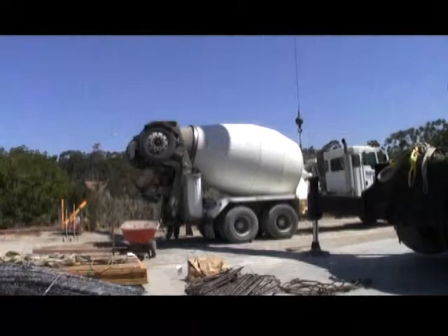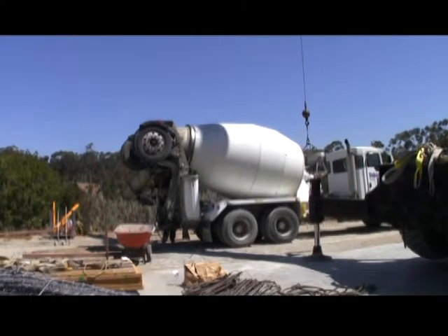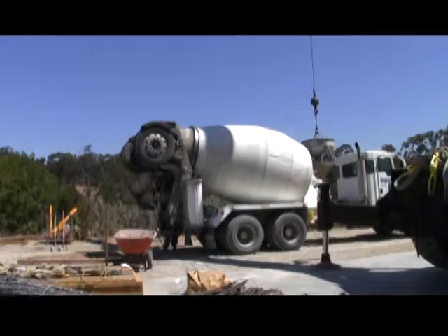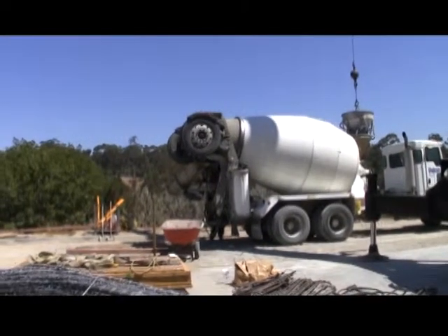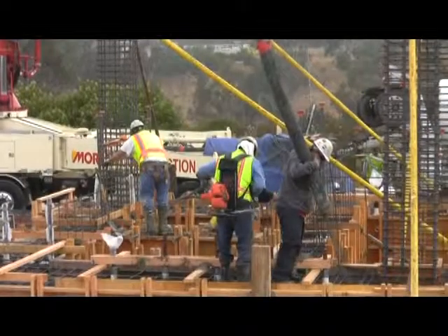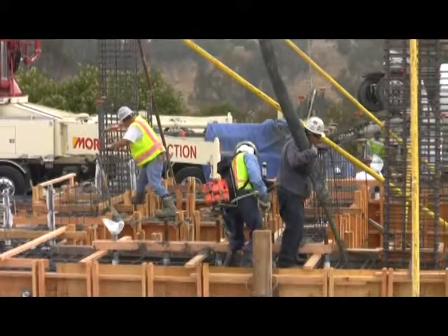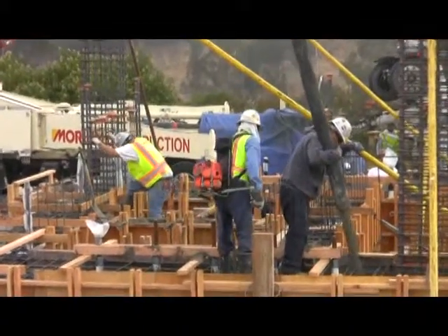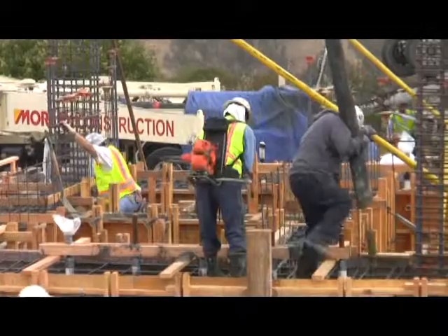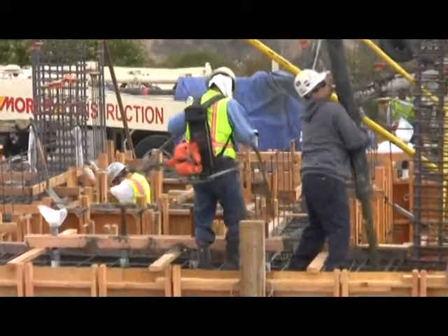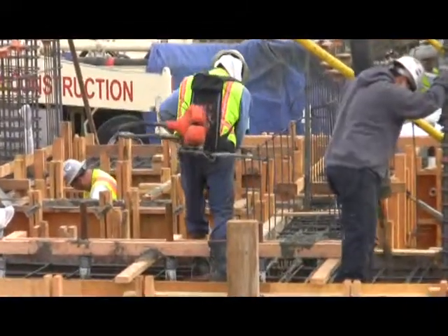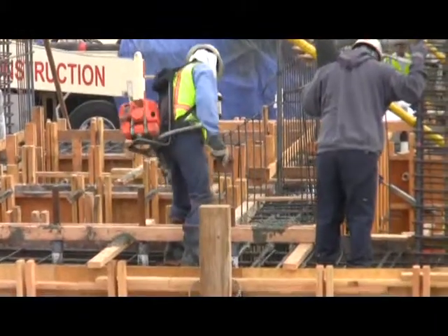In the 5-story building construction, once the desired concrete mix was attained, the concrete was poured into the formwork using the truck-mounted boom pump method. In this method, a wireless remote-controlled robotic arm, called a boom, is used to assure accuracy of the concrete placement within the formwork. Immediately after the wet concrete mix was poured into the formwork, the concrete was vibrated to eliminate voids or air pockets.